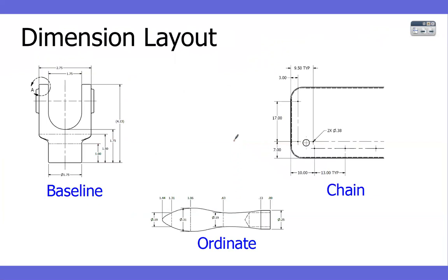But now we're not going out away from the part each time. So I usually use ordinate dimension on things like this, where I'm having a lot of things like that, and on sheet metal for the bend lines. If you guys are going to work somewhere that has a sheet metal shop, you might see that. I use these dimensions other places on the drawing, but for the bend lines, I'll use ordinate dimension. It doesn't take up that much space. So I can easily, on something, have 15 bend lines. I've got hems and different things. I can get a lot of bend lines. That'd make this go like way out here. Half my drawing would be the space for dimensions. With ordinate, it doesn't take up that much space. Okay.